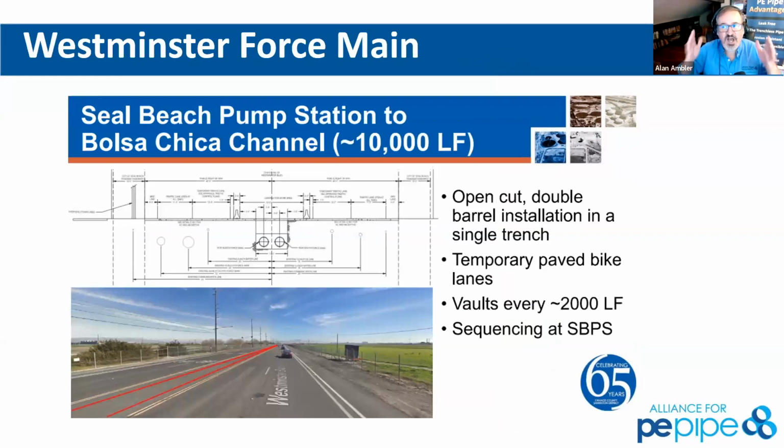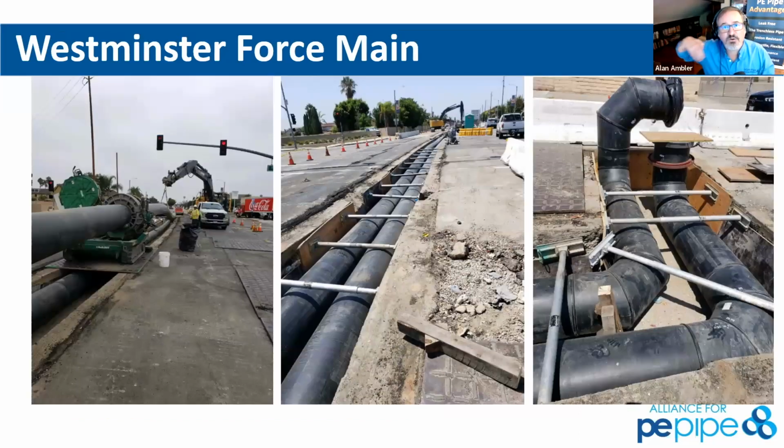They chose a common trench for very long lengths of this force main to be able to get it installed. By choosing a common trench, now we're going, if you could see here, right down the middle of the road. Yes, it may be disruptive for everybody coming one way or the other, but we're going to be able to install both of these pipes in a trench that did not have to be accessed by construction crew to its fullest extent. And we did fuse that above ground in a laydown yard that was away from the project site and out of the MOT requirements, and pull that puppy right into place to be able to make sure that we took advantage of the very long laydown area and open trenches we pulled through it.